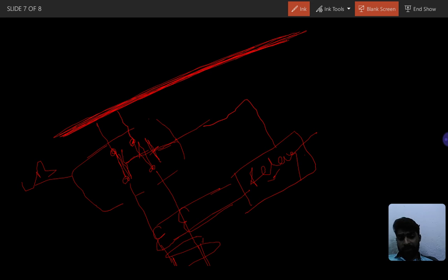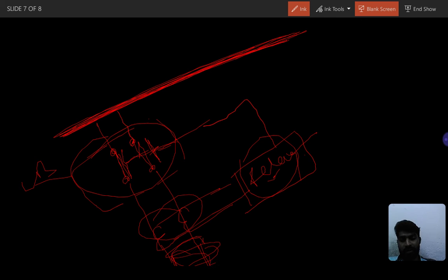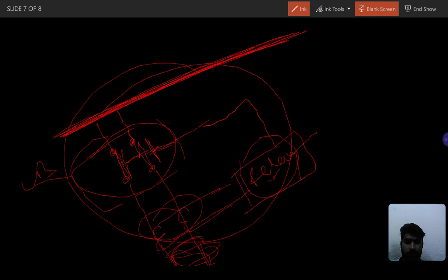Again I'm revising. This is a circuit breaker, this is a relay, and these are CTs, and this is a fault, say a tree falling on the transmission line. We use CT and PT, current transformer and potential transformer, in transmission lines to measure high current and high voltage. Just keep it in your mind. When the fault occurs, the CT will sense that current and the coil gets energized. The relay senses the excess current and sends the signal to the circuit breaker. Automatically this contact will open. This is the overall working of your circuit breaker.